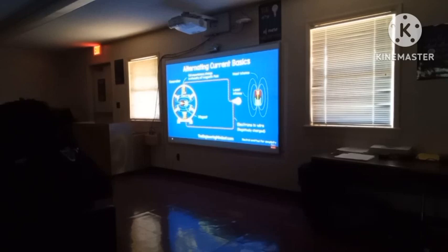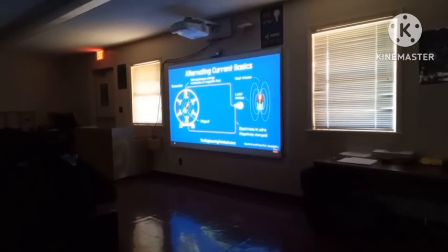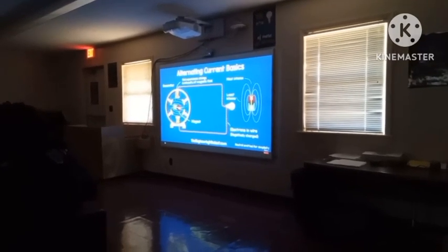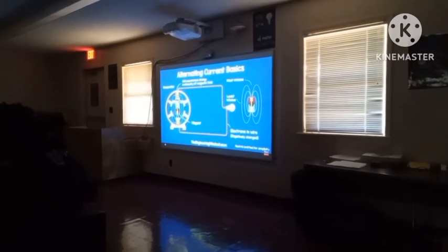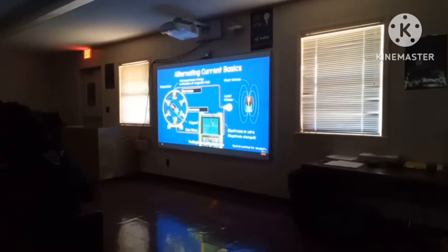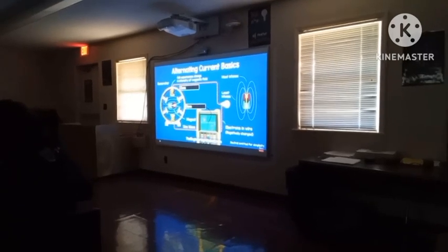This will be from 0 up to its maximum intensity, and then as it passes the coil, it will decrease again back to 0. Then the negative half comes in and pulls the electrons backwards with the same change in intensity. Each full rotation of the magnet will therefore produce this wave pattern known as a sine wave.